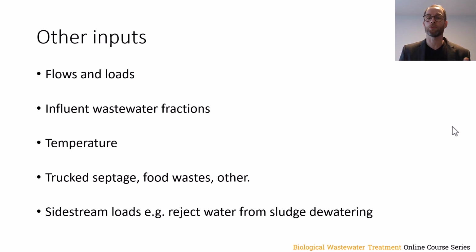They might only operate 1 day a week. And during that day, they may only operate 8 hours because the operator is only on site 1 day a week and he wants to go home at the end of the day. Under these conditions, maybe we need to think about simulating these reject waters from sludge dewatering in a dynamic fashion to account for that slug effect of bringing in the entire load in an 8-hour period 1 day a week.